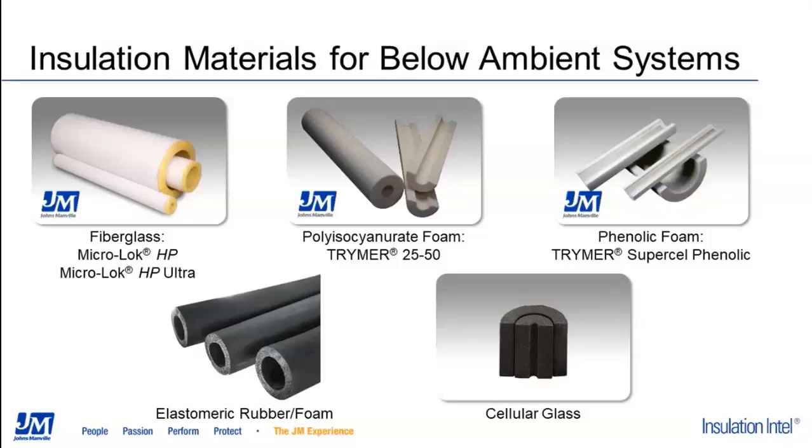There's also polyiso, like JM's Trymer 2550, which is a rigid plastic foam. Polyiso is manufactured as bun stock, essentially big blocks that are then fabricated into pipe sections and fittings. There's also phenolic foam, like JM's Trymer Supercell Phenolic.